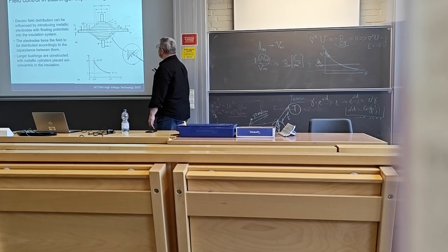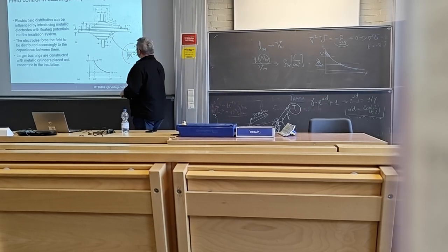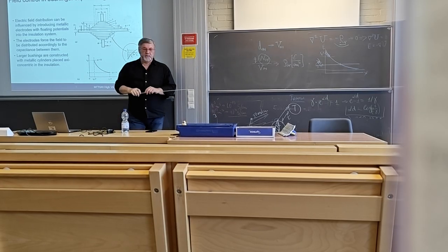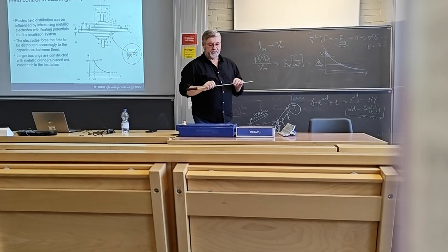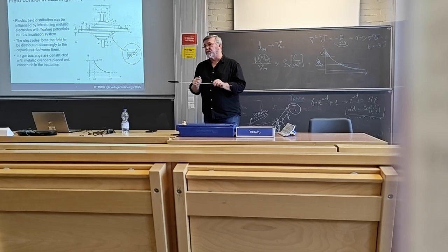Yeah, exactly. That's what I'm talking about. So the selection of the sizes of these layers with the foils should not only be based on the capacitance, but also in consideration of the creepage discharges. So one should avoid internal flashovers between the layers.